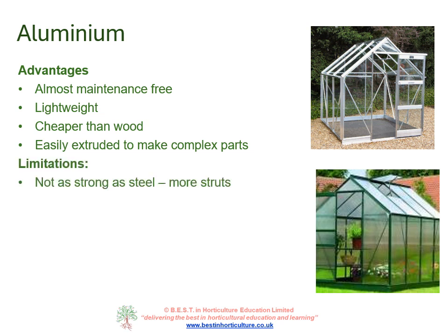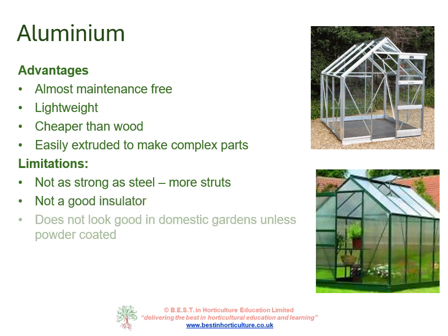Limitations include it's not as strong as steel, so therefore more struts are needed, and this has a knock-on effect on the light transmission into the structure. It's not a good insulator and tends not to look particularly good in domestic gardens unless it's powder coated. And although it doesn't rust like steel, it does corrode with age, and this means that nuts and fixings can seize up over time.